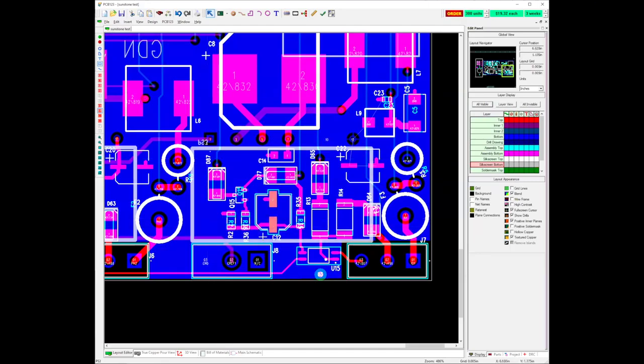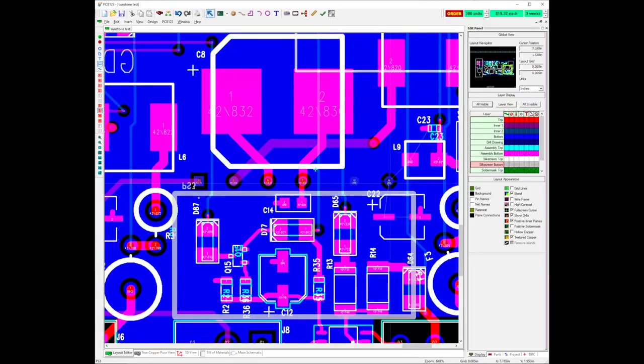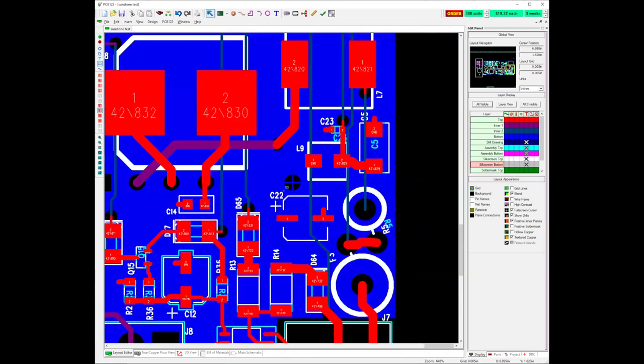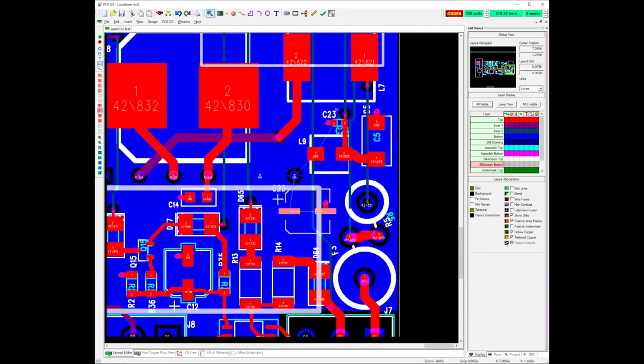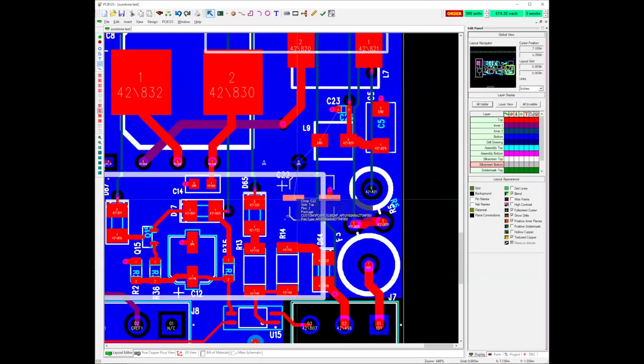You get a short across these two pins, and that's a ground to power short, I think, what I've done. You basically added all of these pins to the ground net, and I don't think that's what I wanted to have happen.